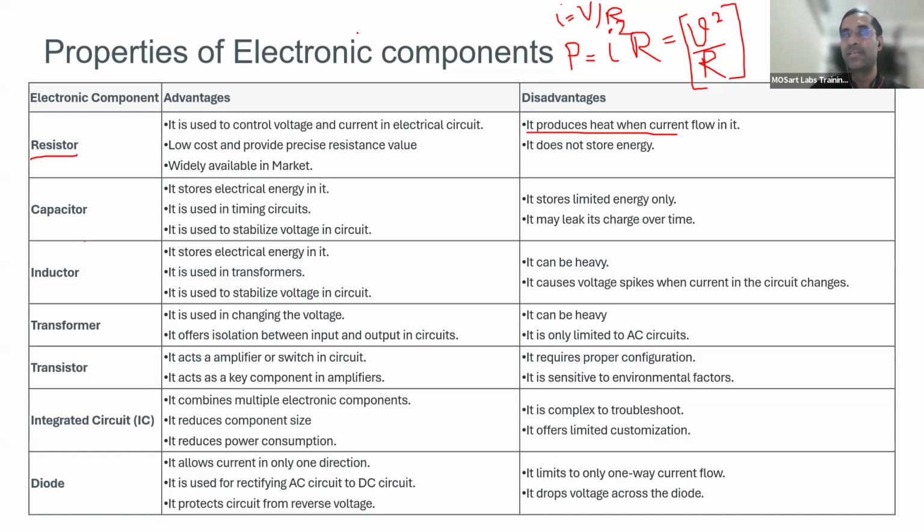Now what happens when things get shorted, positive or negative become short, right? You see a huge current, and whenever there is huge current, the I square R increases, so the temperature of it increases, and suddenly the fuse just disconnects itself to protect your appliance.